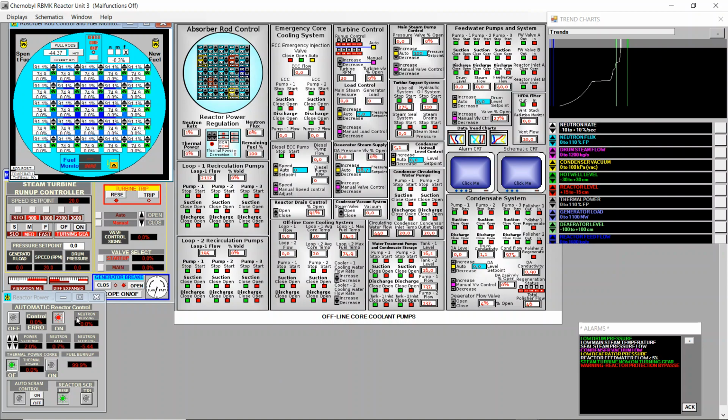So if we were in the BW reactor simulator now, the one from Acme, we can say we're in the source range, really low neutron activity, here at -40 in a logarithmic scale. So now I will not look too much at the neutron rate. Even if I get higher than 10, I will not worry, because I have auto scram control disconnected, and I just want to get this around 0, and then I will be more careful. So I'm just pulling rods in a fast mode, and this was not expected, but okay, this happens. Sometimes you trigger scrams.